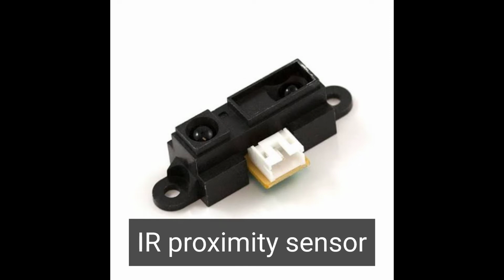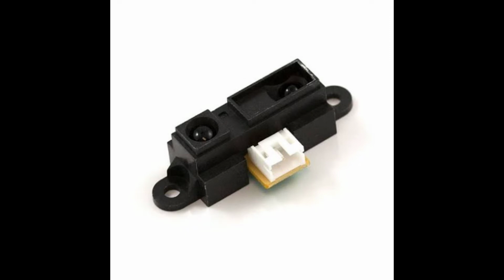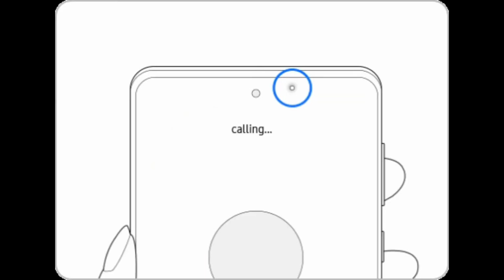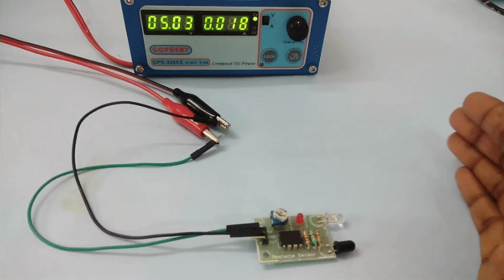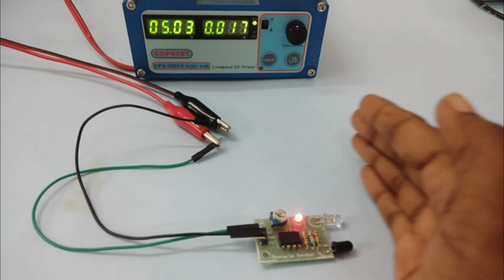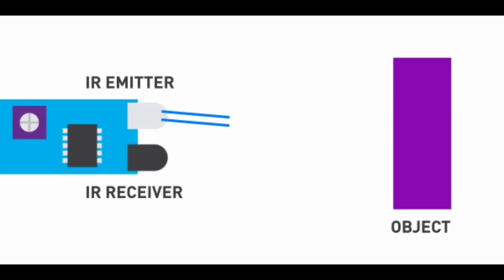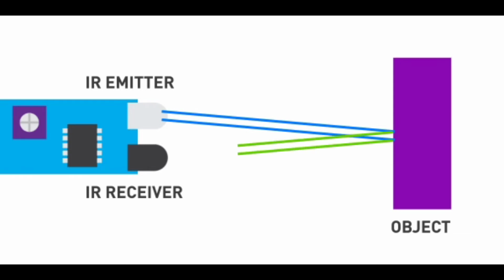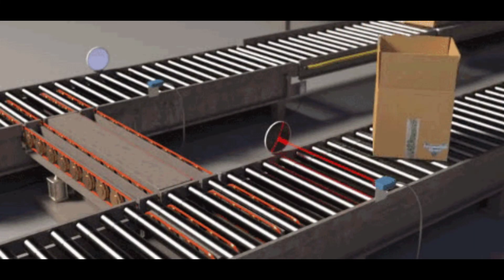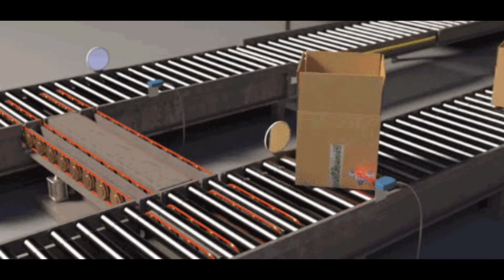IR-based proximity sensor detects the presence of an object by emitting a beam of infrared light. It consists of an IR LED that emits light and a light detector for the detection of reflection. It has an inbuilt signal processing circuit that determines an optical spot. As soon as the reflected light reaches the light detector, it determines the position and the distance of the reflected object.